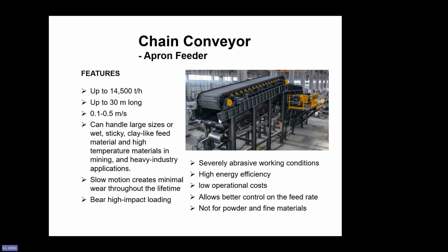Although we have other materials, both materials always contain fine particles. So usually under this apron feeder, we have a pickup belt conveyor, like here, this belt conveyor underneath. So fine particles leak to this belt conveyor, and then this belt conveyor collects all the leakage.